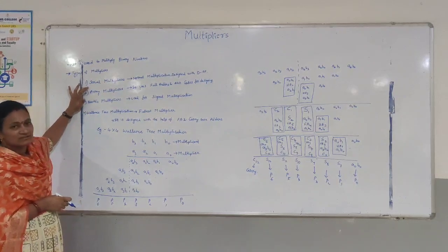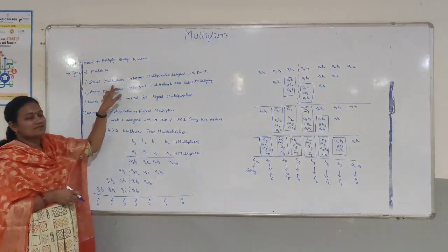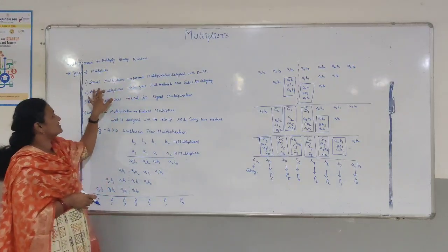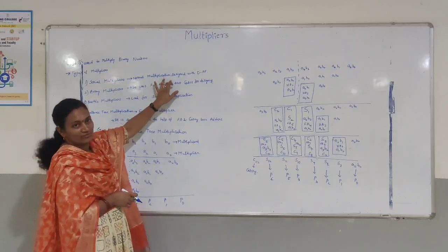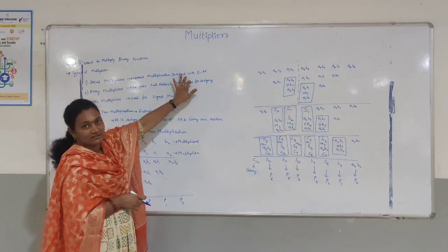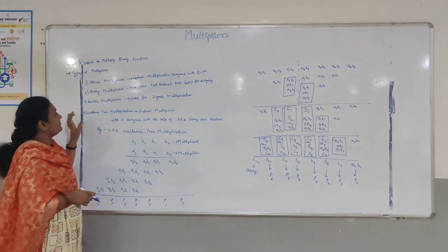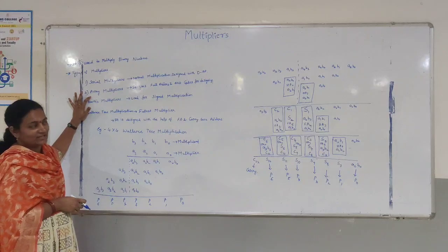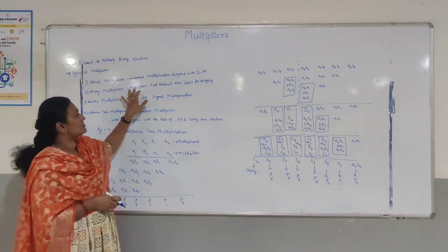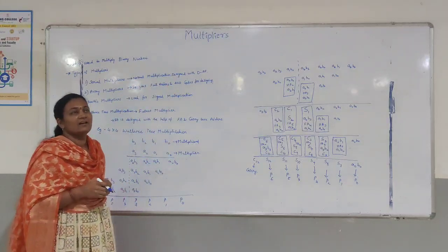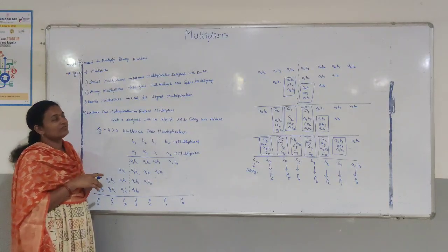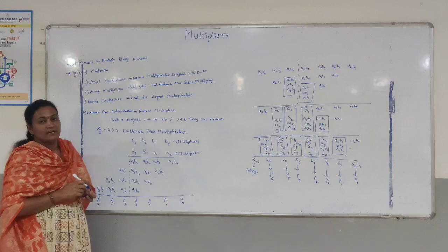First, the serial multiplier uses basic multiplication, and for designing this serial multiplier we use flip-flops, that is D flip-flops, which help to delay the sum and the carry. Next, for the array multiplier, for the design we use the full adder and the AND gate, and the multiplication design is in array format. For that reason it is called an array multiplier.